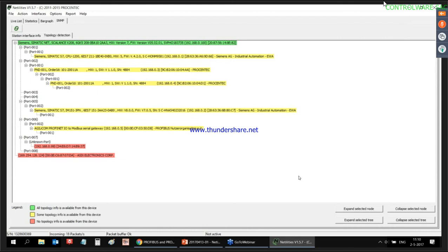You just have a PLC configuration from Siemens, so it's really difficult to find out which devices are where and where they are connected. The flashing information and the topology are really helpful on site to find the device and to find the problem. About the other two methods of monitoring, they are pretty similar.